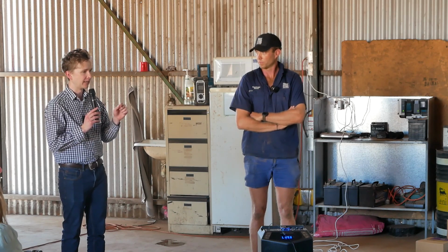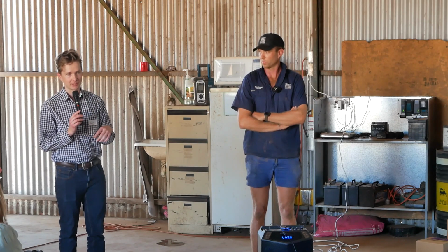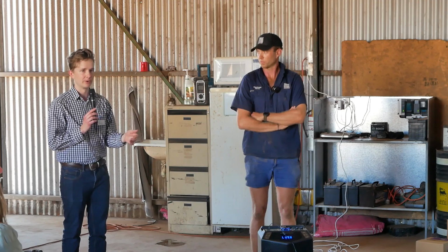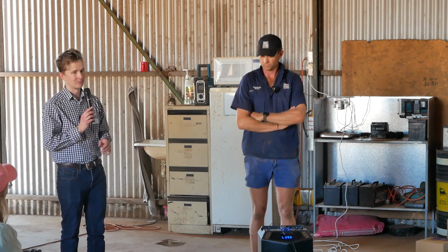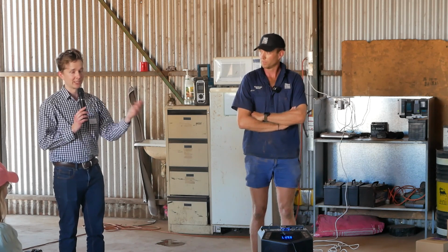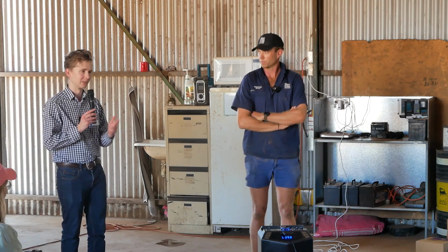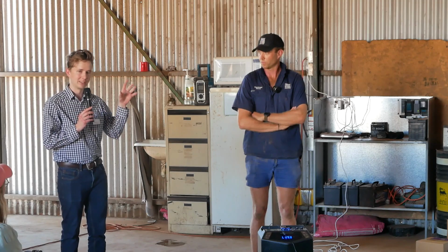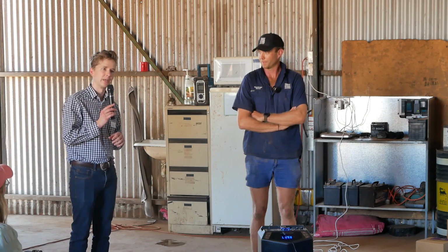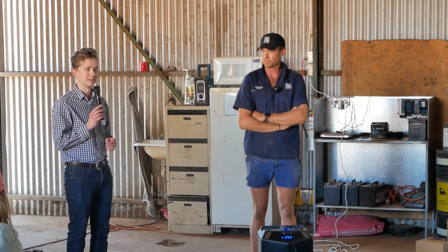The next one is a hybrid mode, so you can detect the cabbage and you subtract the cabbage out of the image and then spray everything else that's green. And that runs a bit faster than the other model and a bit better at detecting, I guess, weeds. And the final one is AI only, where you just run the model itself and then you can spray just double Gs, or you can spray just grass, or you can spray all the weeds, not the crop, or you can spray just the crop. You sort of decide on what you want to do. But it's not as good as detecting the weeds because you have to make the images quite small, and when you make the images small, you miss more weeds. So I think we're still figuring out what the best option is, probably different for different circumstances.